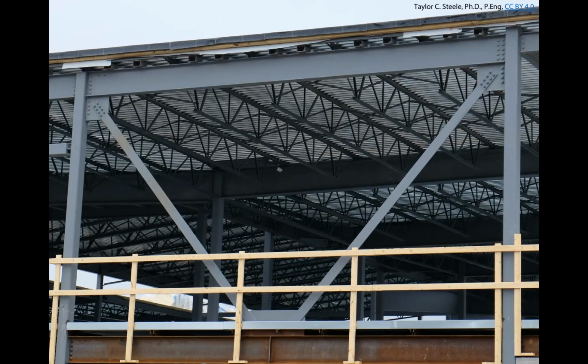Okay, we're going to look at this example again. This is a close-up of that building that I showed you previously, just focusing on the top area. These are the upper braces here. So basically what we have is some tension-only flat bar bracing. They're connected to the gusset plates here with 8 5/8" bolts. And basically what we're going to do is look at what can happen at the brace and what can happen at the net section. We're going to focus on this brace here.